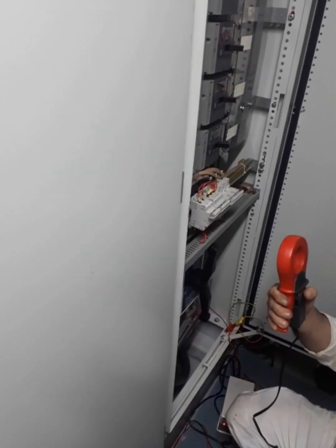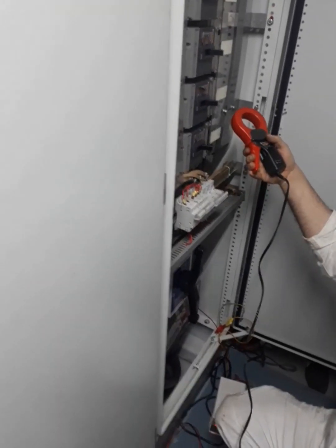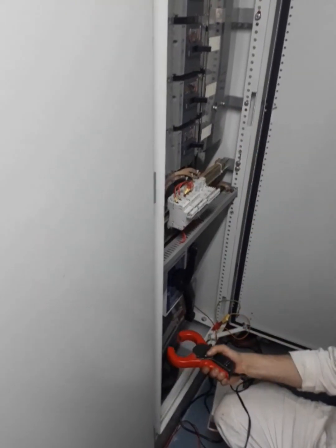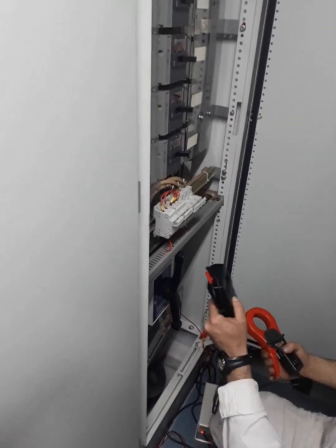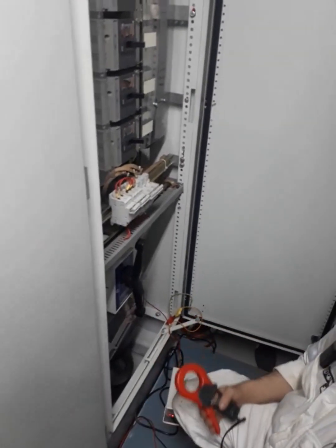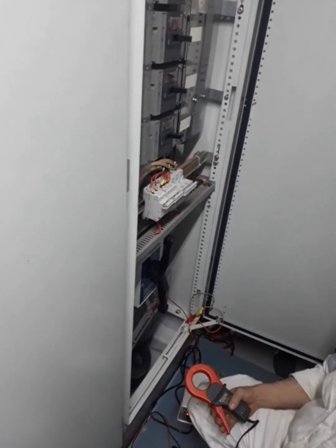Also, you can go there with this clamp on, for example, the cabinet. We don't need to shut down T83. No, because for the Megger we have to shut down. That's why we use this one here, to find the location of the distribution which is grounded. Yes, that's what he'd like to show you.